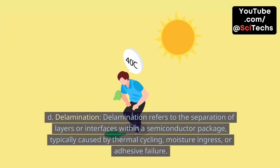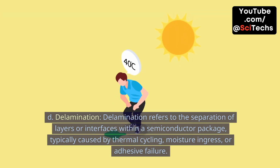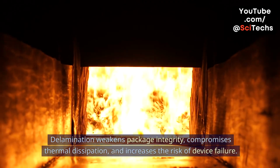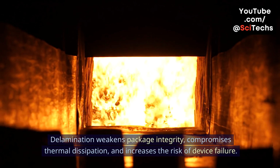D. Delamination. Delamination refers to the separation of layers or interfaces within a semiconductor package, typically caused by thermal cycling, moisture ingress, or adhesive failure. Delamination weakens package integrity, compromises thermal dissipation, and increases the risk of device failure.